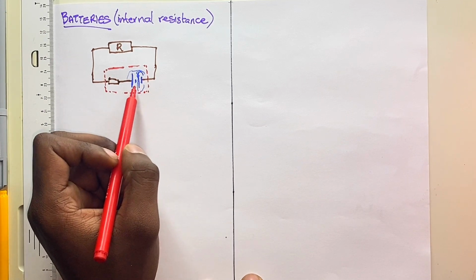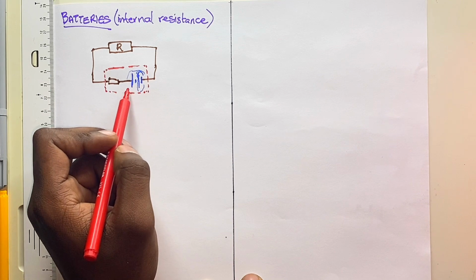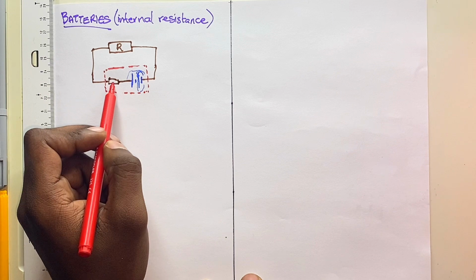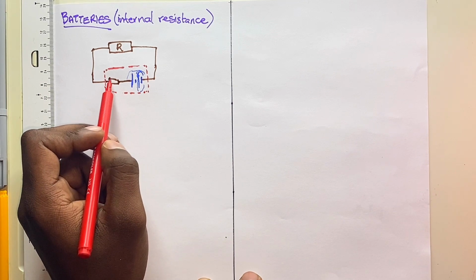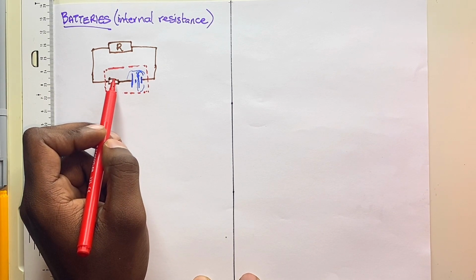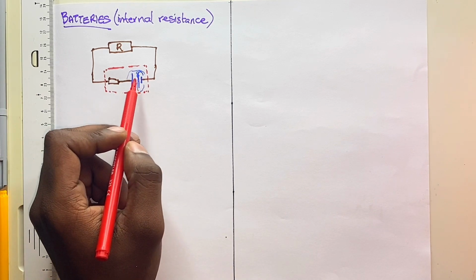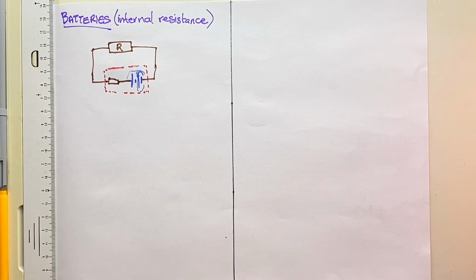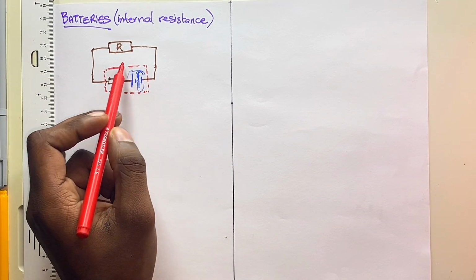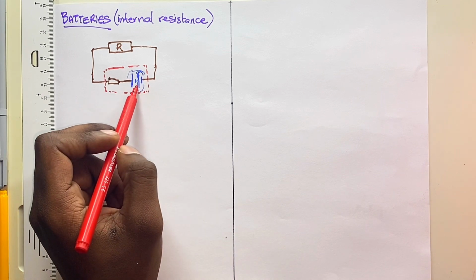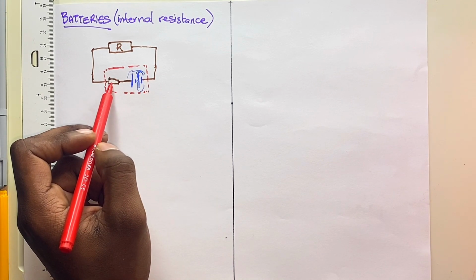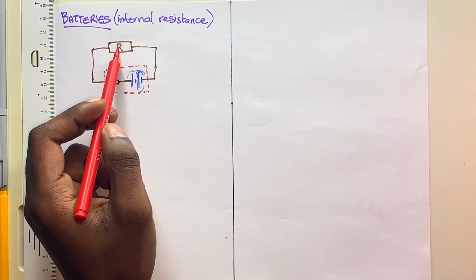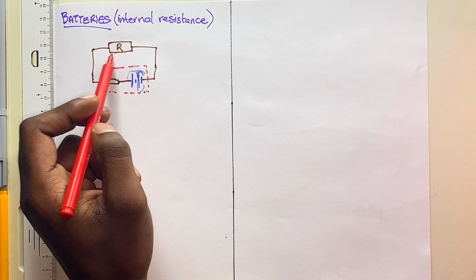It will consist of cells, one or more, each having an anode, a cathode and electrolytes, and it will have internal resistance. This internal resistance is kind of a traffic jam for electrons due to factors like electrolyte resistance and electrode interfaces, but we won't discuss that in this module. So, a battery consists of cells and internal resistance. As electrons flow externally, this resistance will become the traffic jam.